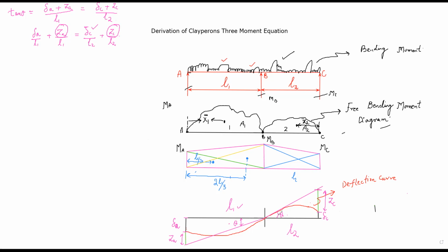What we are doing is drawing a tangent to the curve at this very point such that the tangent intersects with the normal drawn at another point of the deflection curve. And you are taking this ZA as one of the distances. Here the tangent drawn to the deflection curve at one point is intersecting with a vertical line drawn at another point.